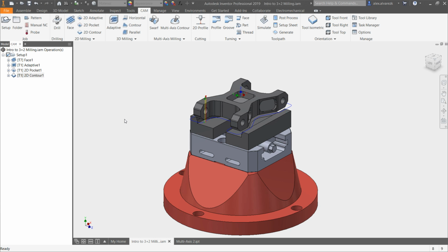With some of those rotations and transitions, you want to make sure that you don't have any collisions, right? So once you start diving a little bit deeper into 5-axis toolpaths, the risk of having some sort of collision really increases exponentially, right? So you guys want to take the time to make sure that you either model something similar or you just bring in the assembly of your vise.